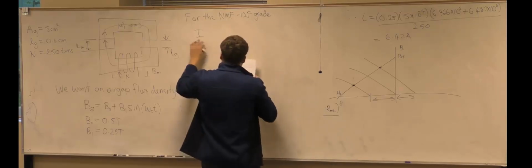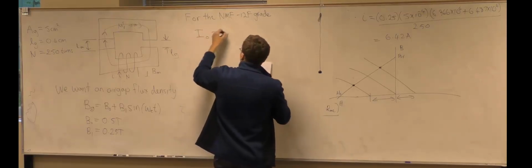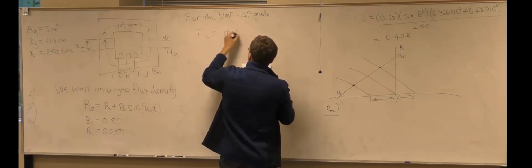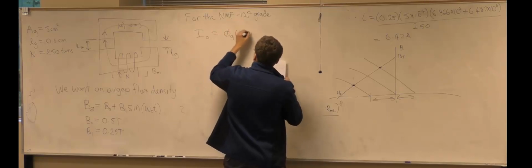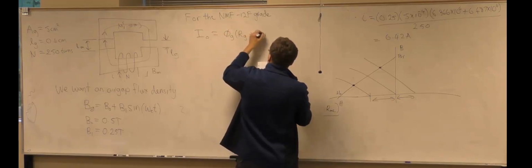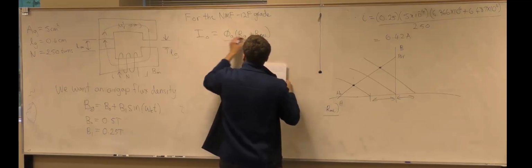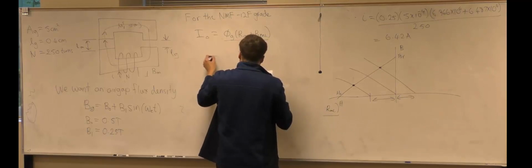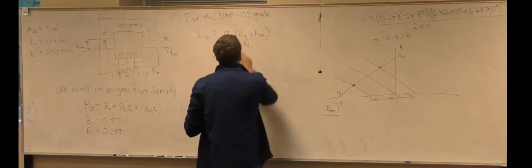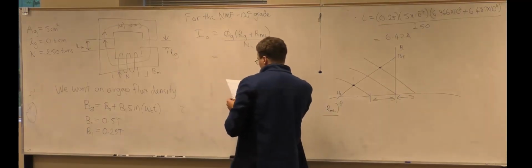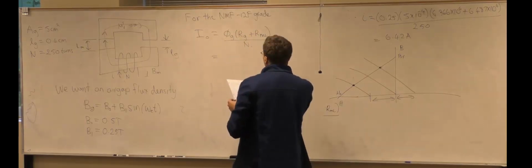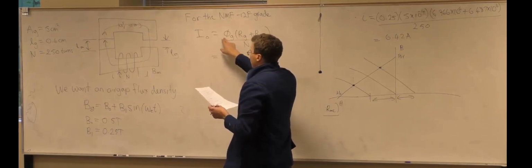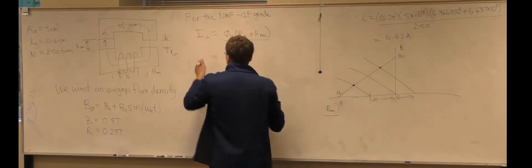So the current is going to be again equal to the flux in the gap times the reluctance in the gap plus the reluctance in the magnet, divided by the number of turns. The RG is the same. The flux is the same because...